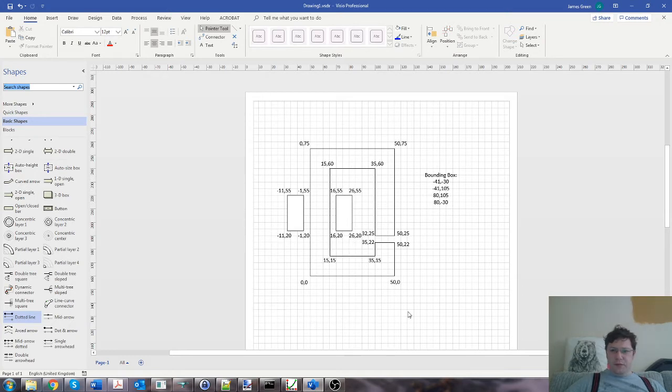So these are the bounding box dimensions. This is all in millimeters, by the way. It's very important that you set it, otherwise you end up with a funny looking problem, or a funny scaling problem. So our origin is 0, 0, and we have 50 millimeters in X, for the sake of argument, and 75 millimeters in Y, and Z is into or out of the piece of paper that we're looking at.